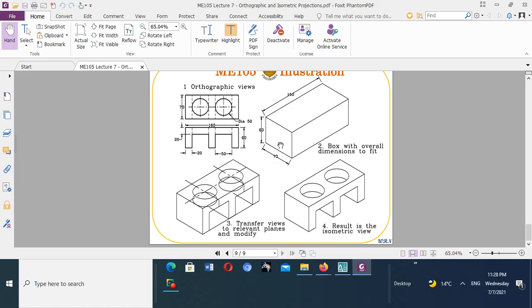How to draw those two circles? Our UCS is to come to this plane, and this will be our drawing plane, and this is our start point. Any of these 4 points can be our start point. This will be our start point. So if this corner becomes our start point, in orthographic this is the corner. So you can calculate the center of the circle. It is in the middle of the 50, so it will be 20 plus 25, it will be 45, right?